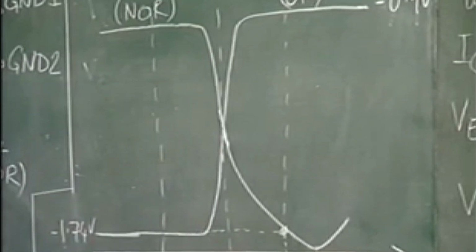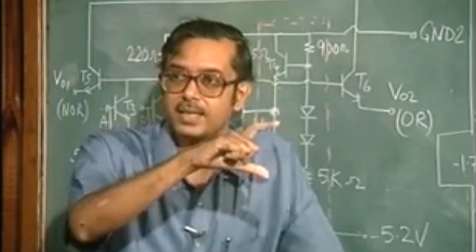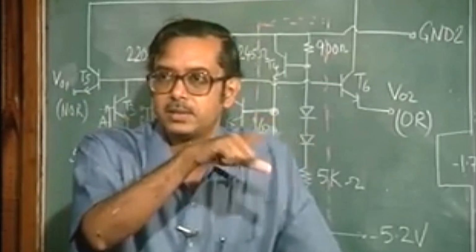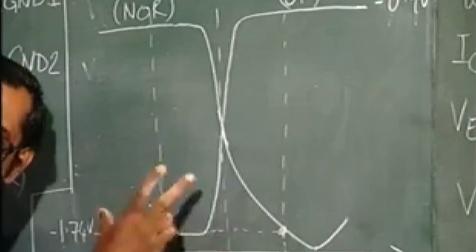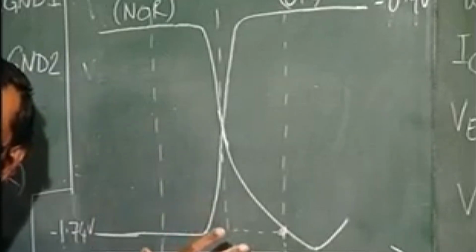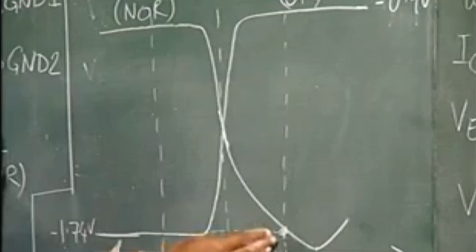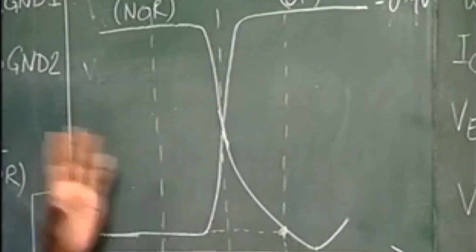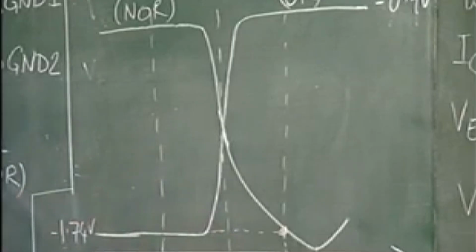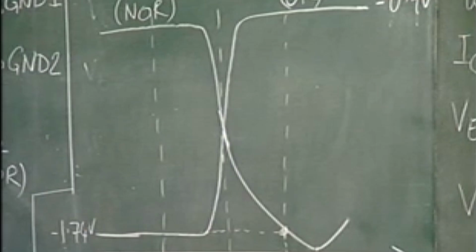So, that is another condition which we have already seen last class, that we have to restrict the input, like we had said VR plus minus half V on. Similarly, here also we have to restrict the input voltage within a certain limit. We have assumed here that the input voltage range is the same as the output voltage range, and if this is adhered to, then the transistors are not going to go to saturation. So, they remain within these limits. Now, for this circuit, what is the noise margin? Let us take it up.